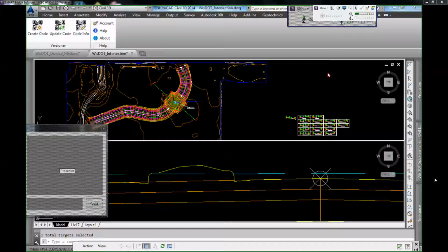Another one I'd like to comment on, it was really great to see the workflow you put together. The offset assembly usage is something we haven't promoted in our training, in our workflows. Early on, and this goes back to the 2010 version, whenever we used offset assemblies, we were having troubles with the corridor surface recognizing the feature lines that we had assigned to it. So it was the problem that we were seeing with your curb, where those feature lines weren't being used to define the surface. We were seeing those types of problems anytime we used offset assemblies.